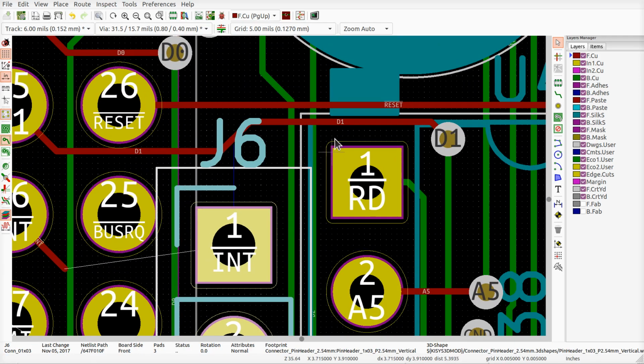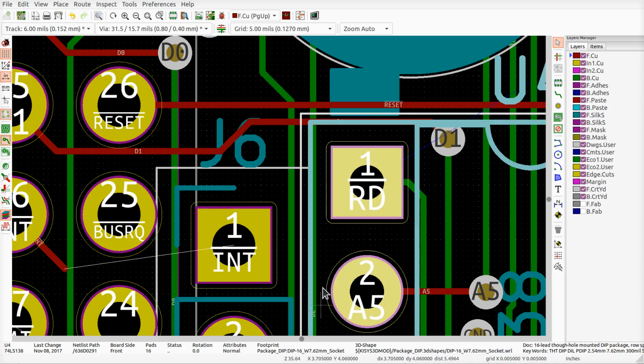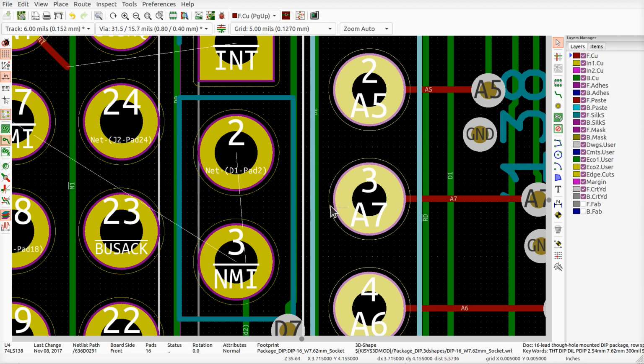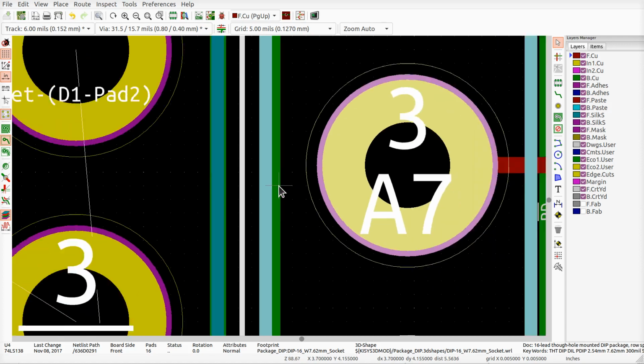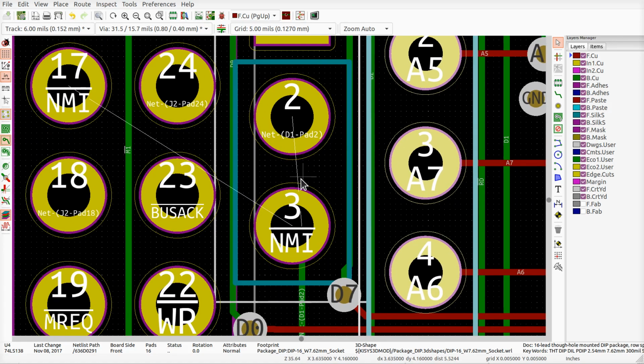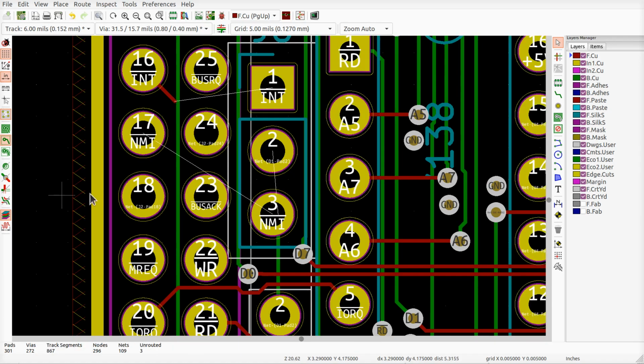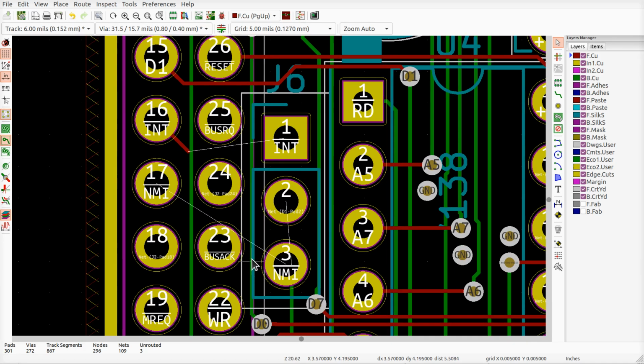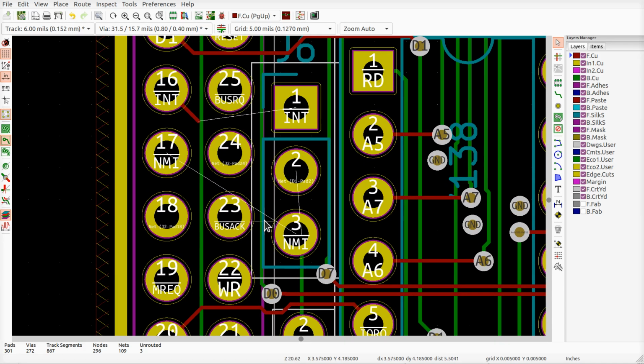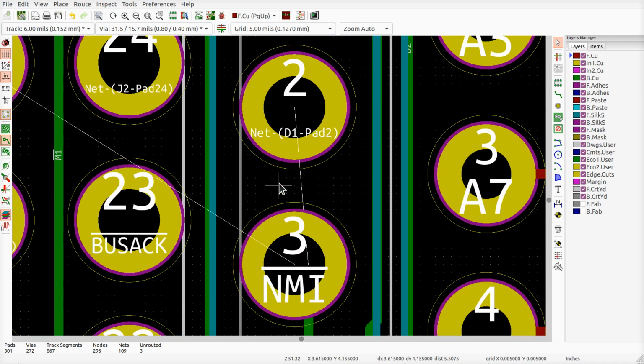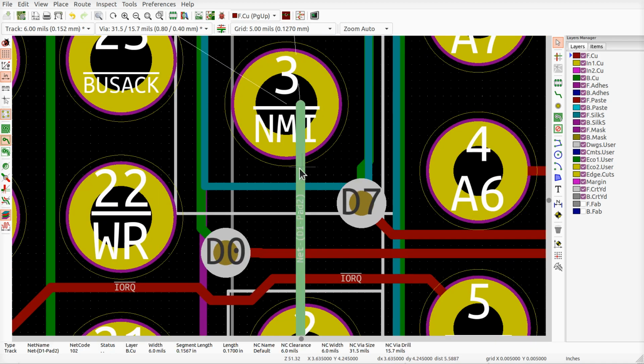Okay? And it's actually not even inside coincident with the chip on the right here. I think this is going to be okay. This is really pushing it. These white lines around here, the courtyards do overlap, and the DRC will gripe. But somehow I will get over it and find a way to sleep at night.